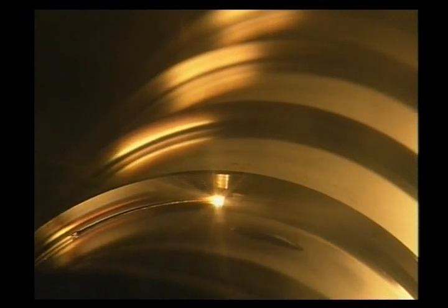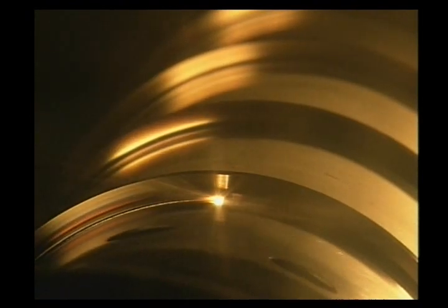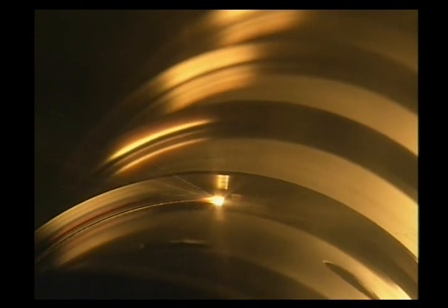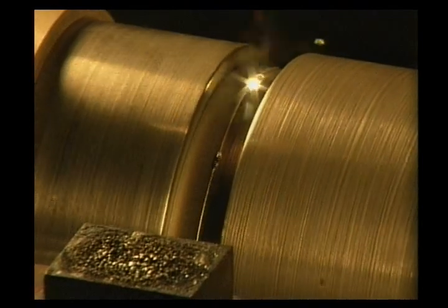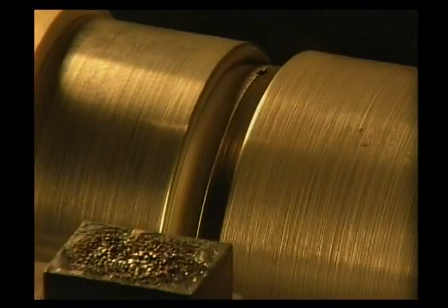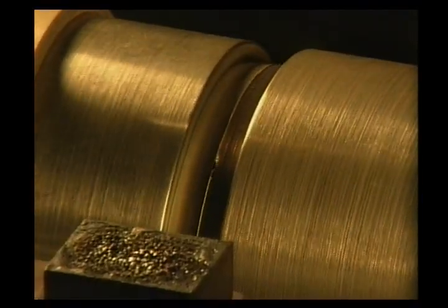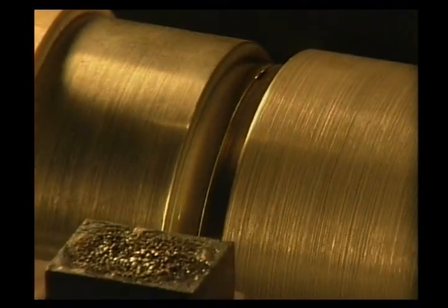Virtually all ferrous and non-ferrous metals, thin or thick, can be joined. Welding speeds are fast, and filler metal is not generally required. Equipment cost for electron beam welding is typically high, and welding is generally limited to machined parts assembled in primarily butt, corner, and lap joints.